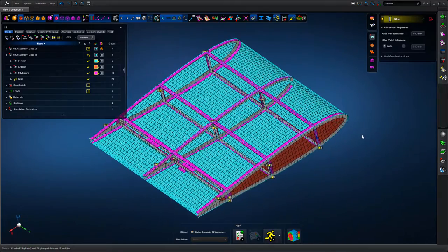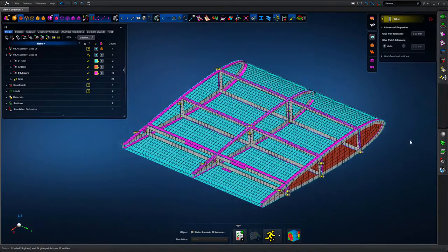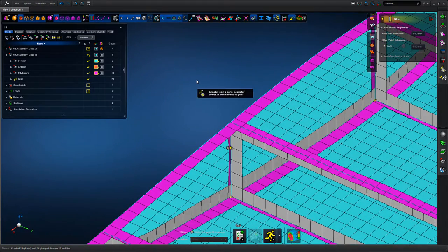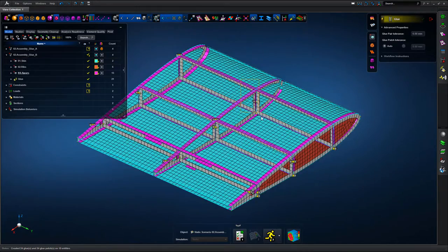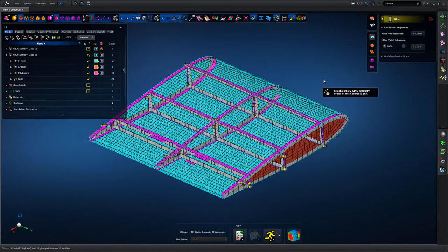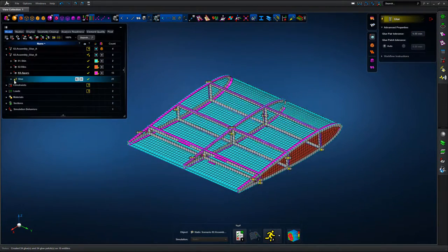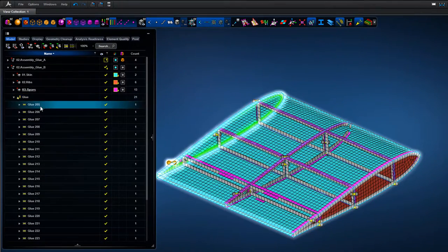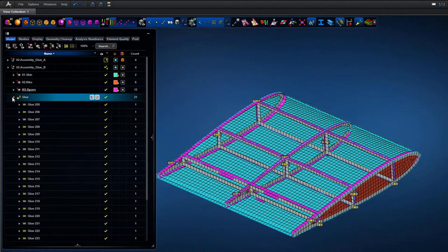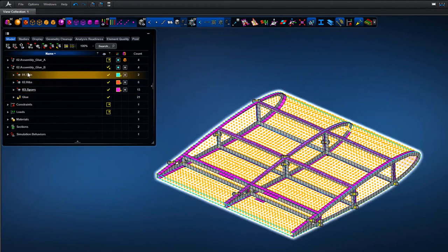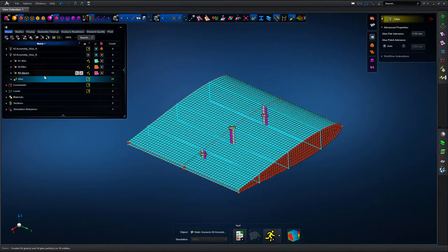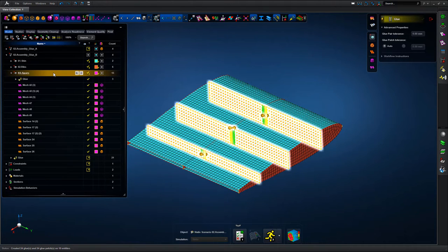And again, using the default parameters, we can see the glue pair patches as defined within a given tolerance, so we can see the new spar in its position glued into the skin and glued into the rib, and equally the cruciform between the spar, rib and skin, we've got the glue pair defined appropriately. So if we expand the glue defined on the assembly level, so these are the glue patches between sub-assemblies, we can see those pair definitions and highlight them or modify them as necessary. And if we just show the spar defined on its own, we can see the glue patches at that level.